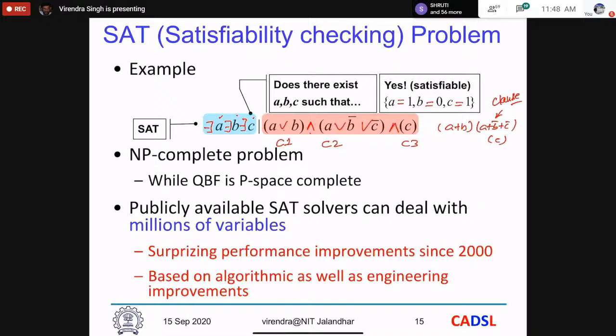So in two-SAT, if you have only two variables, one input and one output, it is always deterministic. All the clauses that you can use are deterministic. And therefore if I know the output, there are no choices you need to make. What can be the circuit that I can make out of it? A chain of inverters, right? Yes, sir. That's the only possible circuit that I can make.